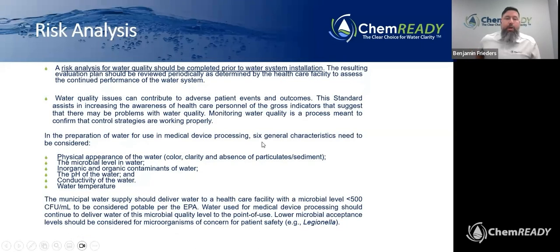The risk analysis for water quality should be completed prior to water system installation. I know a lot of facilities already have water systems. That doesn't mean that you should not do this. The risk analysis still needs to be performed for your existing system to understand what parameters your system is capable of creating, what the risks associated with each piece of equipment could be, and how they could contribute to adverse patient effects or outcomes.